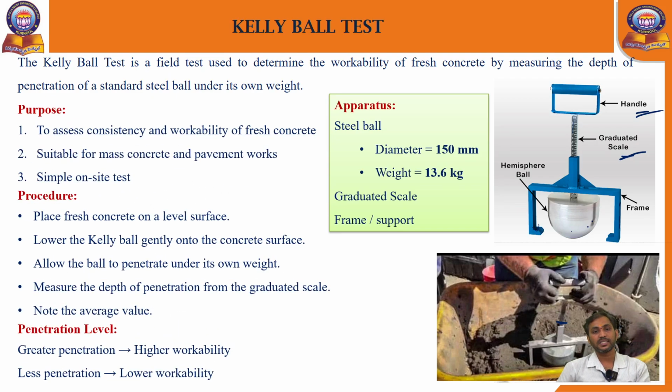Purpose: to assess consistency and workability of fresh concrete, suitable for mass concrete and pavement works, and also a simple on-site test. Procedure: place the fresh concrete on a leveled surface, and lower the Kelly ball gently onto the concrete, then release your hand slowly.